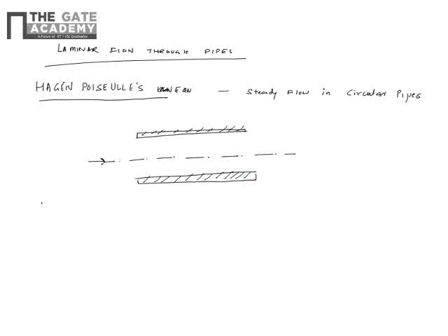The cross section is uniform. So let's write what are the basic features of this derivation. The cross section is the same throughout, so no change in velocity of the flow. This is because the volume flow rate has to match: A1 V1 is A2 V2, and because A1 is equal to A2, V1 is equal to V2. Now here we consider the flow to be viscous.